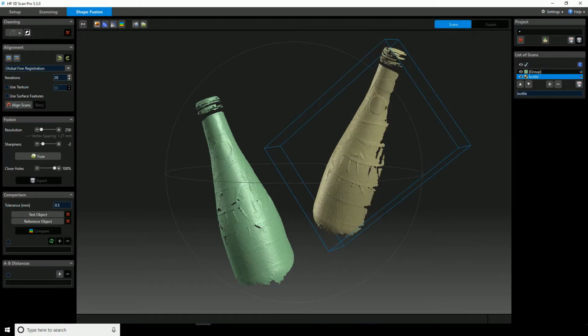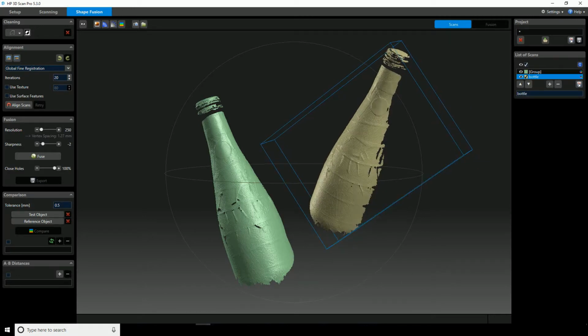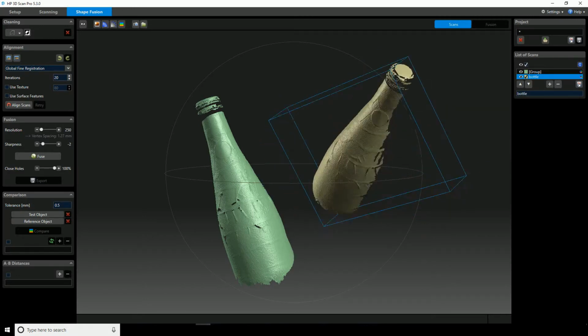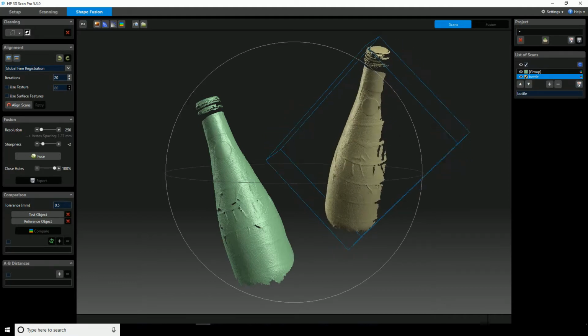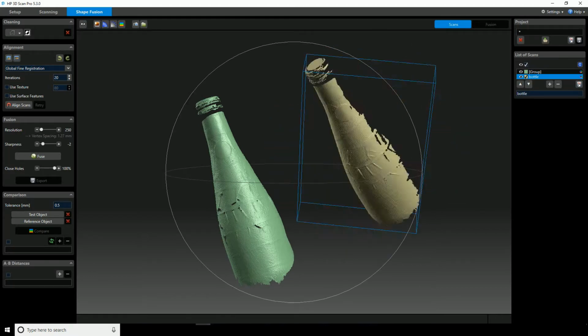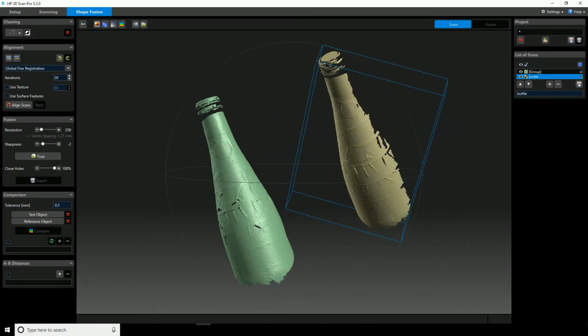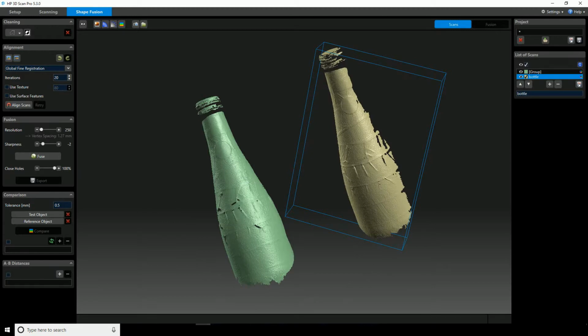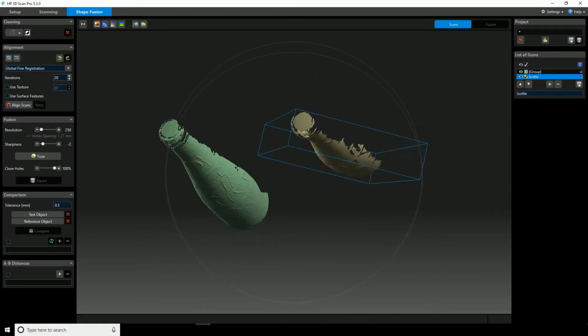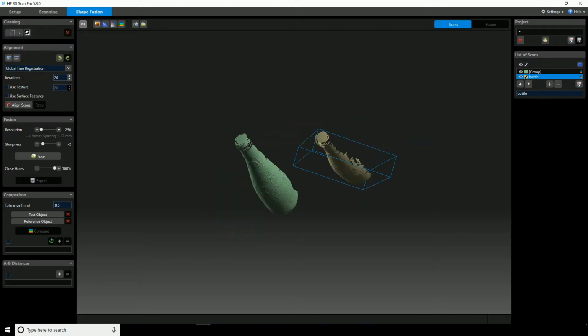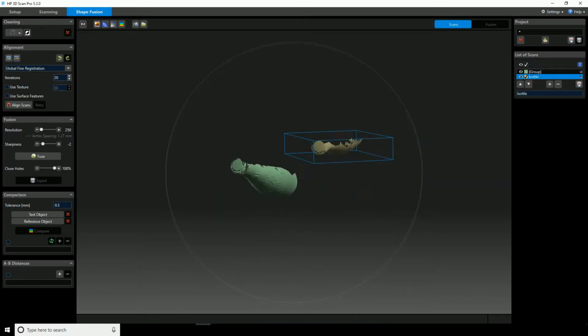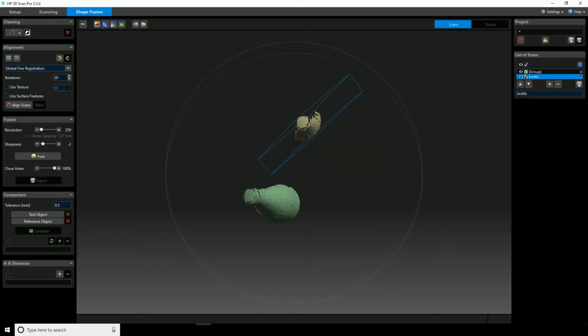We can, using the right key, and inside that circle, if you can see the sort of big circle that's going around the top, around like that, with the right key, inside that circle, I sort of go forward and back with the model. Outside of the circle, I'll go round the clock, like a clock hand. And a mixture of the 2 should help you orientate those. Again, release the shift key and you move both models together. If you want to put them back in the center of the screen, use the auto adjust or the A key. There we go. Do you know, I can get myself really confused using these.